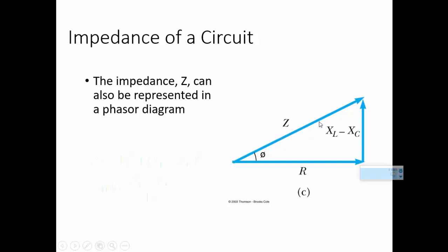We don't mainly call it resistance, we call it impedance. You will get used to the Z very soon, but for now, if I get the voltage triangle, I can easily transform it into the impedance triangle. I can multiply everywhere by current and still get back to my previous diagram. This is what you get in terms of the impedance triangle. We have the Z here, which is this one right here with the angle, and we've got the resistor underneath there.